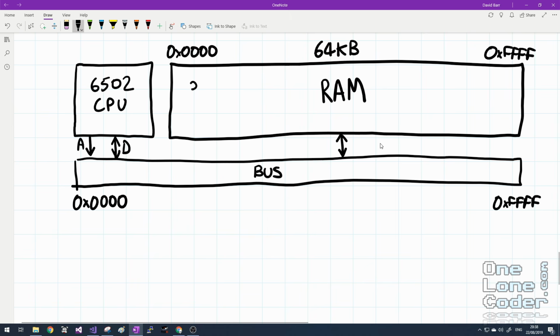And not only is it going to contain the variable information we might use in our programs, it also contains the programs themselves, which is a fairly traditional von Neumann architecture. This implies that most of the time the CPU is indeed extracting bytes from the RAM in order to execute them as parts of its program, and periodically it reads and writes to different locations to act as temporary storage.